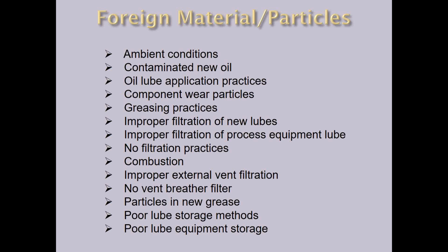What about greasing practices? I go to the plants all the time and I see particles on top of the grease zerk. The guy comes by, wipes it off with a dirty rag, puts his grease gun on there, so particles go into the grease bearing. Improper filtration of our new lubes, or no filtration of our new lubes. Improper filtration of our process equipment. Sometimes your equipment in your plant builds up particles, and we have to put a filter cart on there and clean those particles up. The lube sometimes is still good, but we're getting wear just from the particles in the lube.